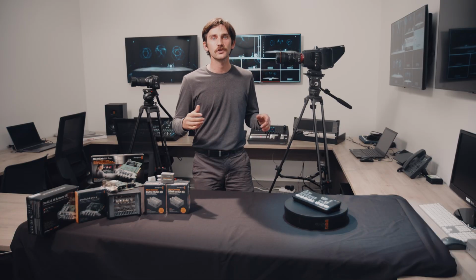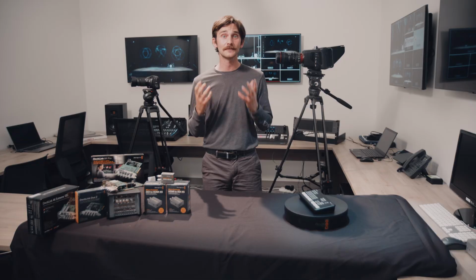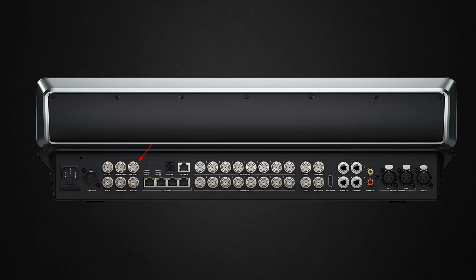The television studio units also function as substantial broadcast mixers, with MADI digital audio in and out, dual XLR and quarter-inch TRS inputs, 5-pin XLR and a network jack, each for TalkBack comms input options, and 2 USB-C connections for recording to an external drive. And lastly, for connectivity, the television studio has 4 10-gig network ports to function as a